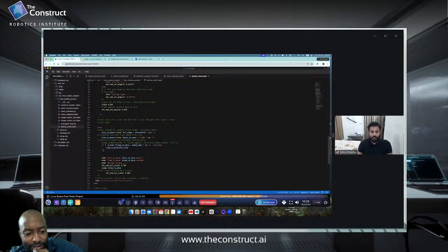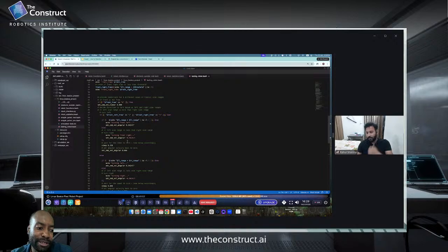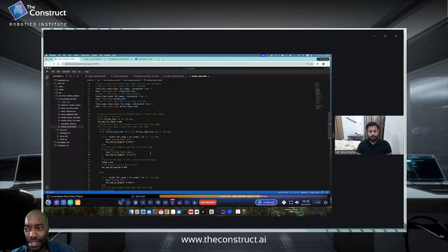All right. So I think it's small enough, but you can think about this case as you go on, right? It depends on how close the obstacle is before you set the minimum time to move. I'm assuming you did a whole lot of testing to come up with 0.5 as a safe time.